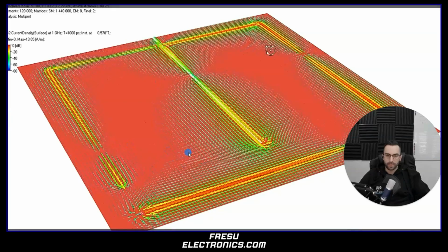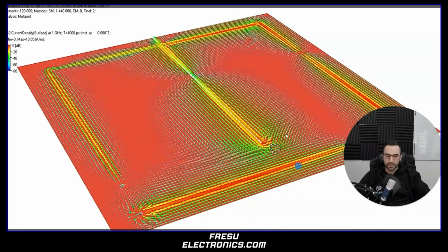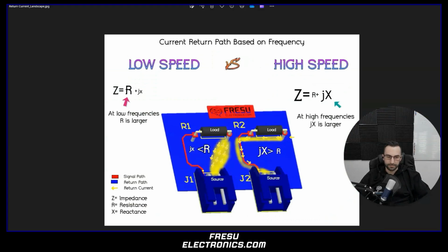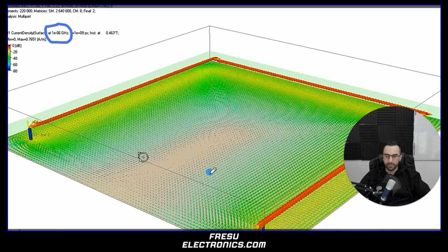And this is what is going to cause not only issues in terms of signal integrity, but also in terms of electromagnetic compatibility, because at this point we have uncontained energy in here. And this is basically what becomes an antenna for our design. And then here we have also the case where we have the return path, which is at a larger distance from the signal trace. Still, it does not return back like in this case, because the frequency right now is still too high for the signal.